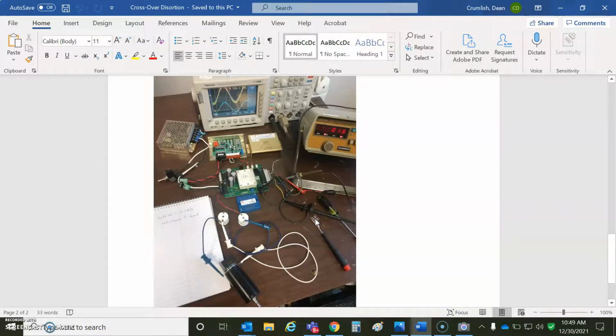I would have to say that some of the old brush motors have tachometers, so this is not a tachometer drive. You'd have to use one of the plus drives if you had a tachometer, analog input to close and tune the loops, and that would require software. But typically these are used in applications where you just need a dumb drive, good quality, nice H-bridge, volts and amps, and then some outer controller measures position and sends a command for current.